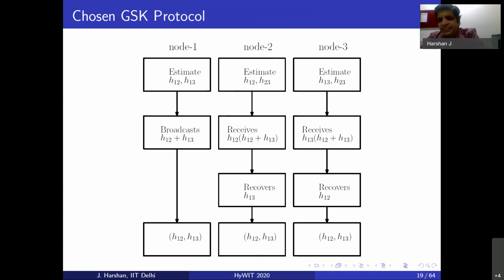And typically an ADC has about 14 to 15 bits, and these are all high precision numbers, right? And then broadcasting these numbers as they are is not practically possible, because usually any wireless device broadcasts using a finite constellation. It could be, let's say, 16 QAM or 256 QAM, or up to 1024 QAM, or whatever it is. Even then, if we want to go to 1024 QAM, there is still a mismatch in the precision of the ADC and the size of the constellation.